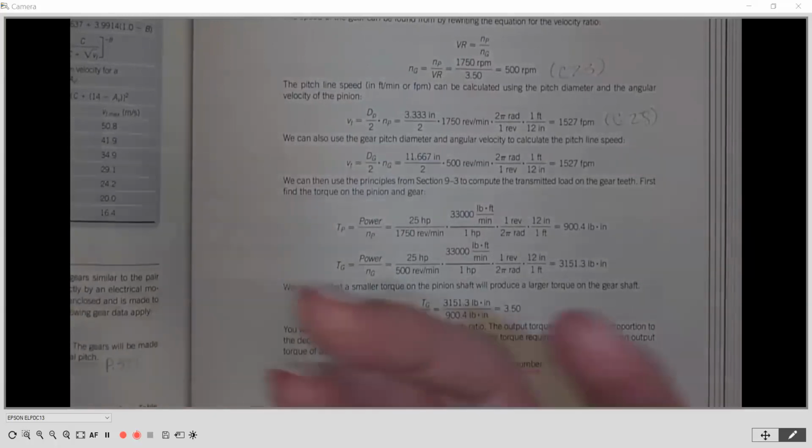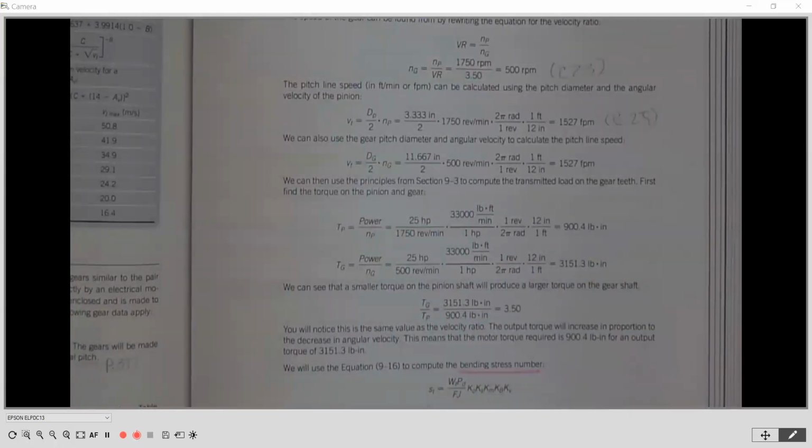So by increasing our torque, that lever arm, we're increasing its ability to do work. And so when we put our case of water on our conveyor, it's not going to stall out on us. It's going to keep going along, right? So torque is exactly that. And that function is because of the physical distance, that radius that we increase from the smaller pinion to the larger gear, right? Cool. All right.